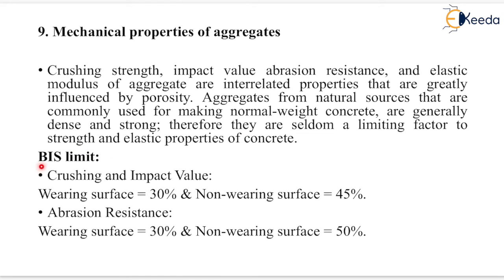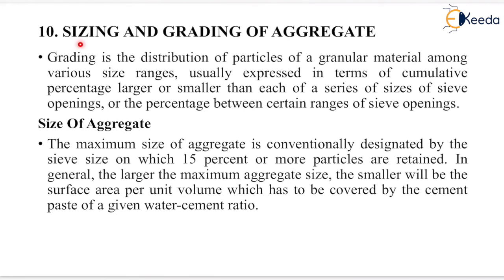Now Bureau of Indian Standard limit for crushing and impact value, that is wearing surface equals 30% and non-wearing surface equals 45%. Now for abrasion resistance, the wearing surface equals 30% and non-wearing surface equals 50%. Now next is the sizing and grading of aggregates.